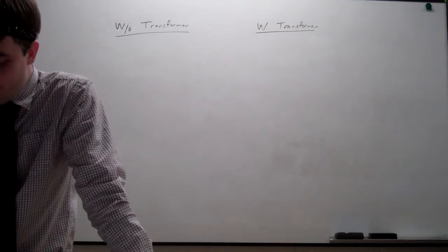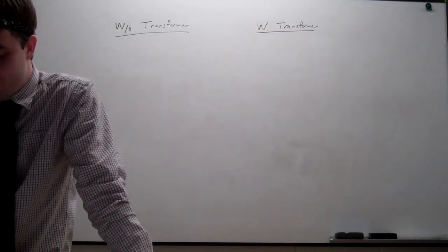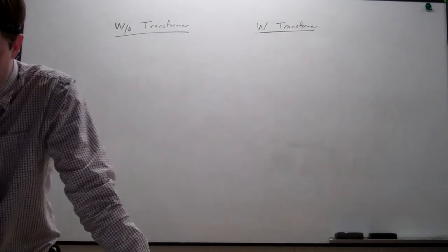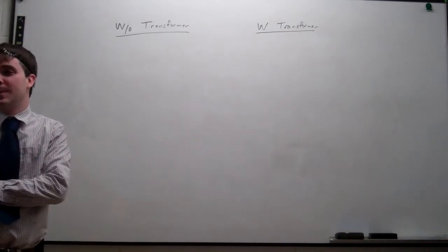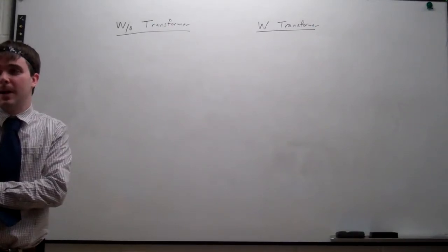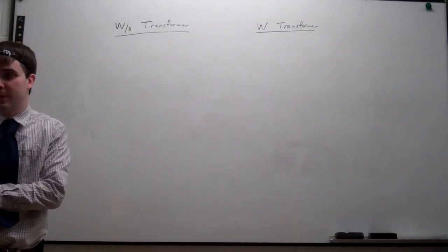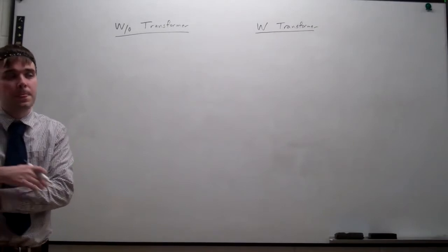All right. What is the percentage of the power loss when the voltage is stepped up, and when it isn't? So we're going to have to find the total, and then find the power lost. Divide the power lost by the total, and then multiply by 100 to get the percentage for each of them. Does that make sense, everybody?